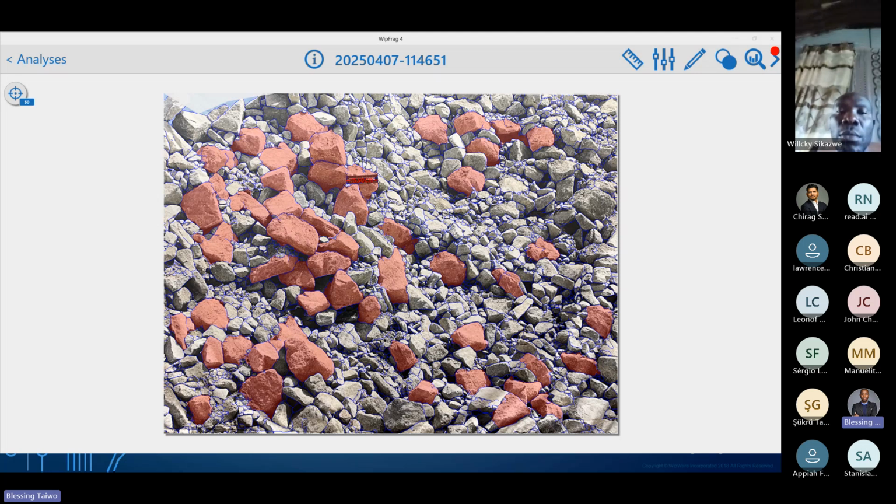Maybe I need to investigate the rock strength. Sometimes the strength of the rock at that section might vary. It might be that there is an intrusion that has higher strength compared to this section. It could also be that there is blowout. Maybe you need to increase the stemming in this area. Maybe there is discontinuity, there is fracture. Then you can easily investigate the drilling operation to see the penetration rates during the drilling in order to track what is going on at this section.